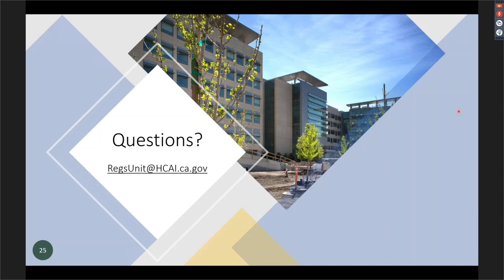You're asking for a clarification for a dimension that's not shown on the drawing, but it doesn't change the location of anything. You're just saying this is 12 inches from the wall. You can just answer that on an RFI. We don't need to see that information. You're probably going to add it to the drawings and cloud it and delta as the RFI number. We don't need to see that.